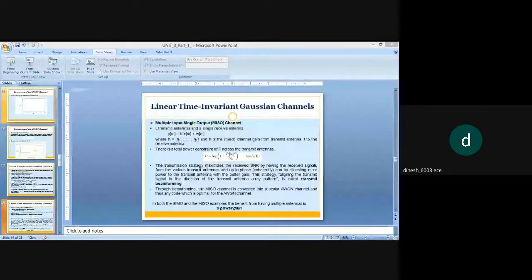And the function varies from 0 to maximum bandwidth W. So the optimal power allocation converges to P star of f, which is 1 divided by lambda minus N0 divided by |h of f| squared. So this is your water filling mechanism scheme. So the power allocation can be interpreted as water filling over frequency.